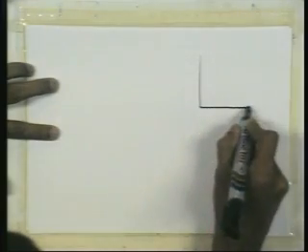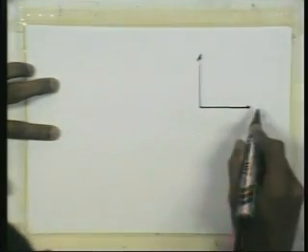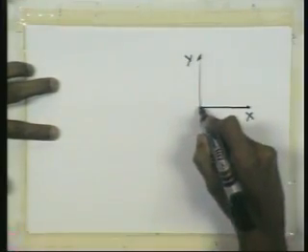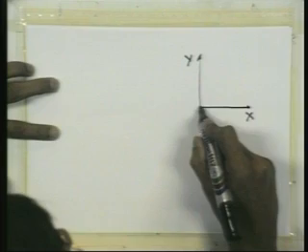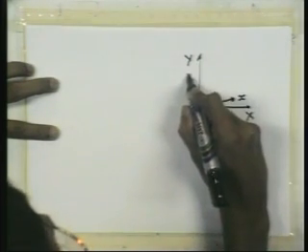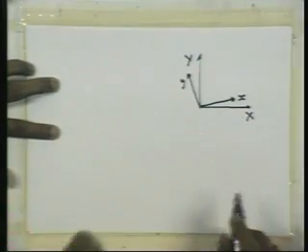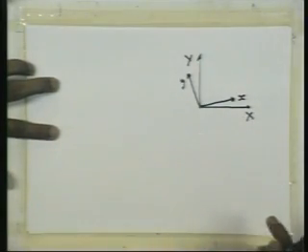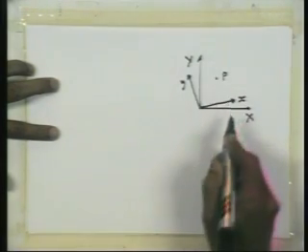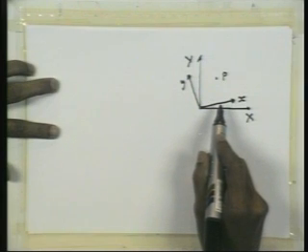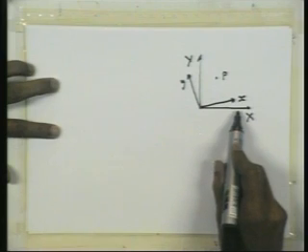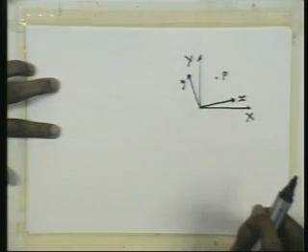So if you look at a very simple case in the planar case, let's say this is a global x and y axis, and z axis is out of this plane, and the local xy after a rotation about the z axis is this. Fine. In transformation, what do we do? In transformation, if you take a point P in the local frame, right, that we know its coordinates in the local frame, we find out its coordinates in the global frame, right.